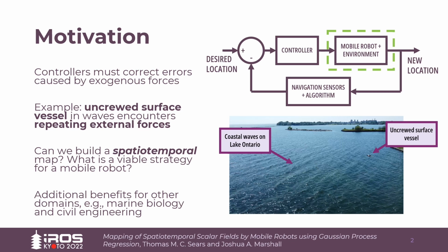As illustrated in the control block diagram, typically environmental disturbances are either unmodeled or use a static model. We would like to replace this with a time-varying model generated in real time from onboard observations. Now, such a strategy would benefit any vehicle affected by structured or repeating forces, but our focus is eventually to use these techniques for an uncrewed surface vessel encountering surface waves.